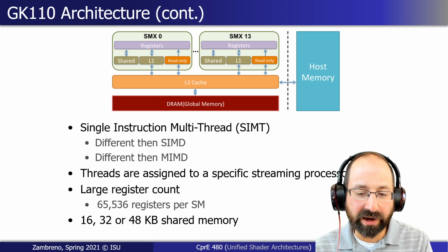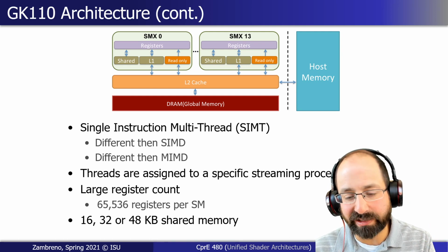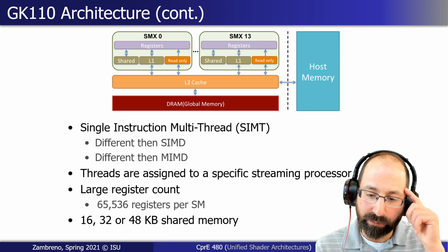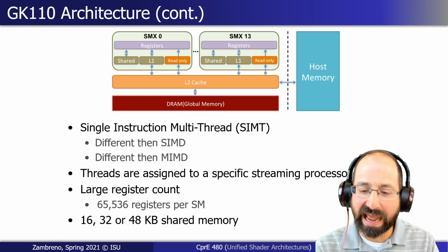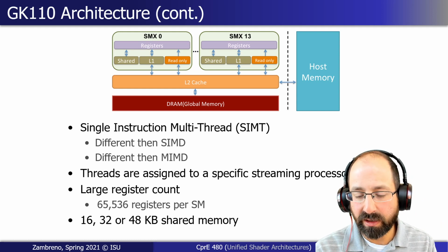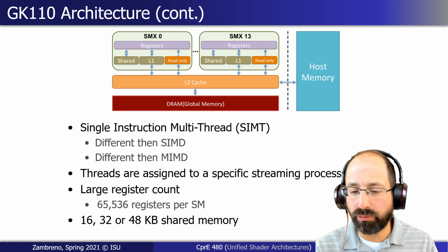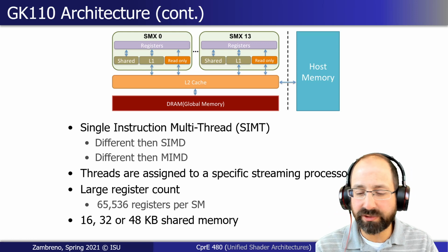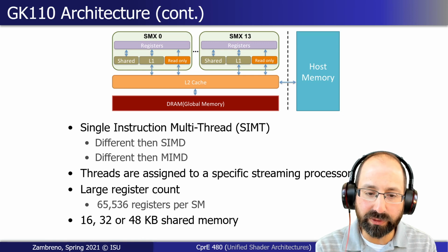So instead of a regular scalar add instruction in our SISD architecture, you would have a vector add instruction that would take 4 pairs of values and add them together independently, or 8 or 16. It's at that level of parallelism. You wouldn't have a 1024-element block of data addition in a single instruction. So 4, 8, or 16, something of that level. That is the traditional way of parallelizing on a data level.